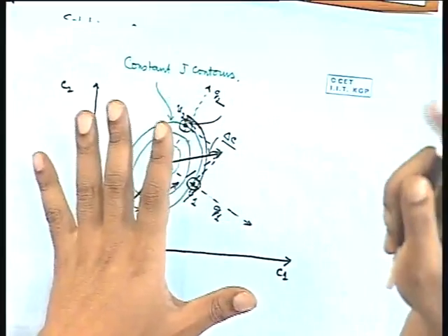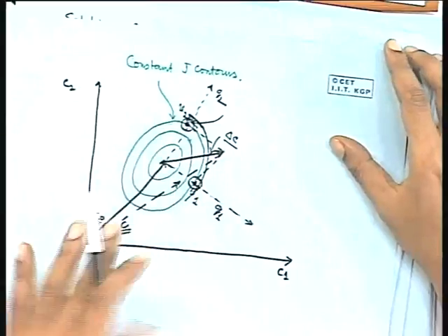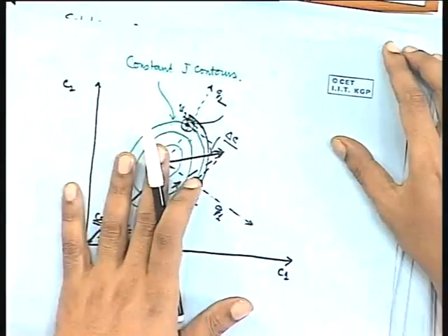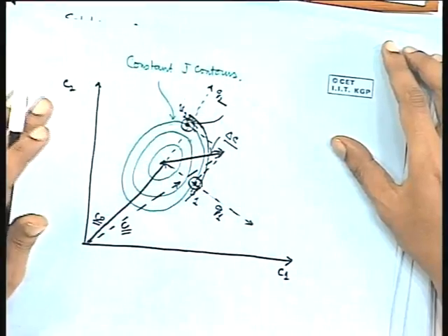Later on, when we discuss adaptive filters, we will see that if I want to adapt the weights, change the weights, how do I prove whether this adaptation mechanism is going to be stable? How do I know that these weights will not explode? So I have to prove certain things, and breaking onto these coordinates will simplify matters to a great degree, in the sense that we will get scalar differential equations rather than vector differential equations. So you see that by breaking up my error, I can characterize penalty in a nice manner.